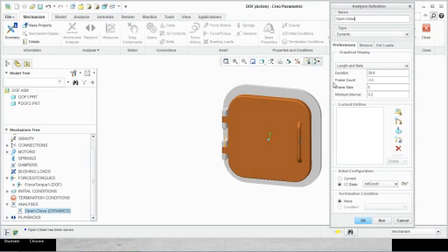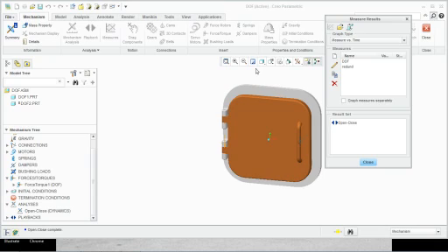Okay, so look at this. It says it has 1 degree of freedom. Because there's nothing stopping it from moving, it says it has 1 degree of freedom, which is 1 rotation, and there is no redundancies. That means there is no other connection kind of repeating the same thing, right? Making it redundant.